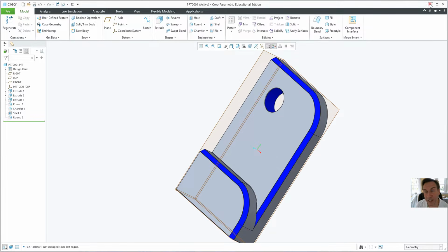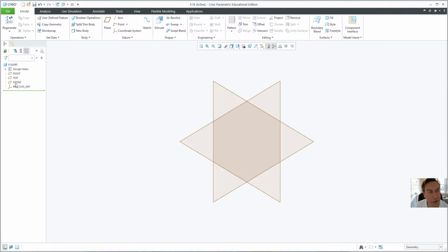So let's start. Okay, the first thing we're going to do is we're going to select the front plane. Now, what plane do you start with? Quite honestly, in this class, most of the time I just sketch on the front plane. Where it comes in handy is, let's say we have a remote and you're designing this. Someone says, okay, design this. Now, where do you want to start? Well, I want to draw this rectangle right here on, that's probably the front. So draw that on the front plane.